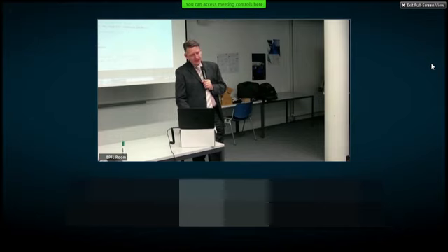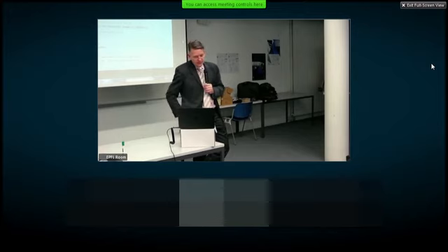The nature of the information: is it analog? Is it digital? Is it wireless? On the analog side, we're essentially talking about some signal, some voltage, and there's been a lot of work done on ADC, analog to digital conversion, and then the opposite is digital to analog. Depending on how many bits you have available, you're going to have some discretization errors. A purely digital interface we refer to as DIO, digital input-output. And then, of course, wireless, the 802.11 standard, which is very important these days.